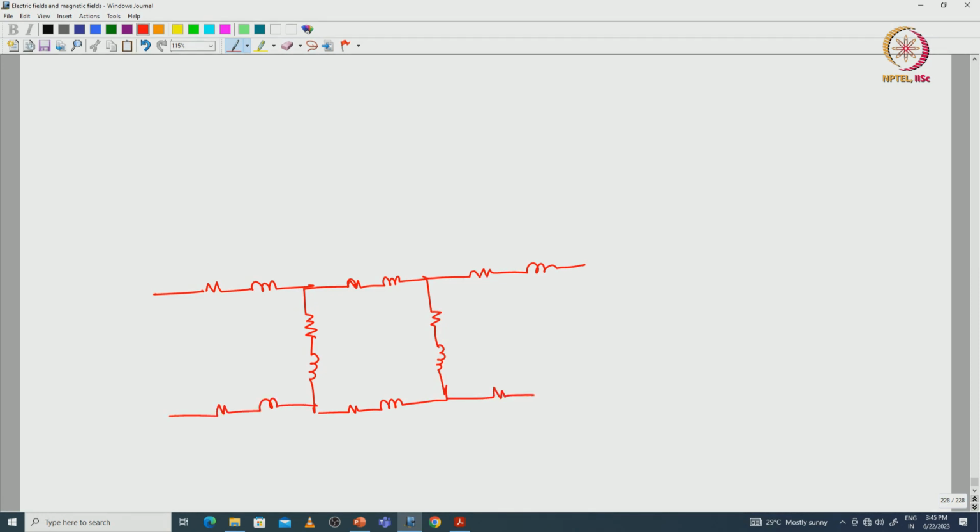If we see the rotor mesh, it is nothing but a combination of resistance and inductance values. Like this, there will be n number of bars, and end rings also, 2 circular end rings will be there. We can see here, this is one end ring on one side, and on the other side one more end ring is there.